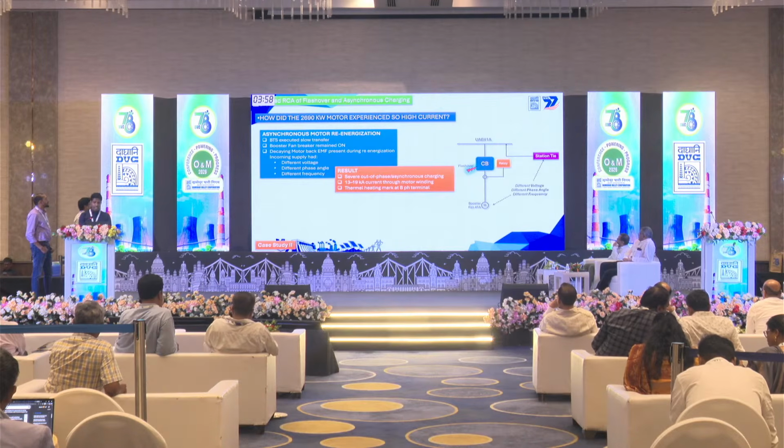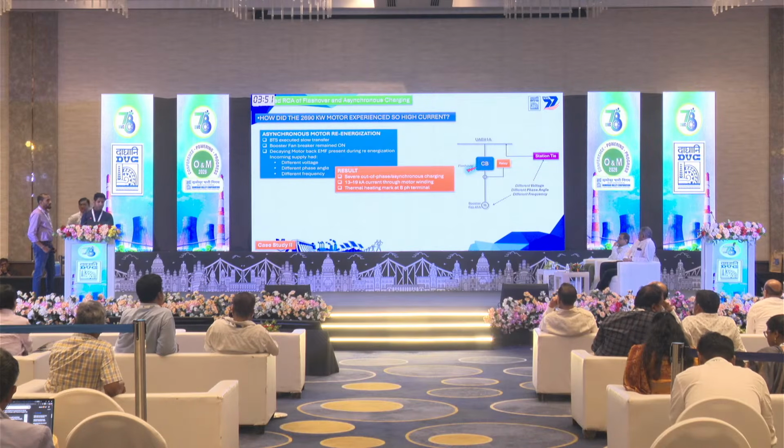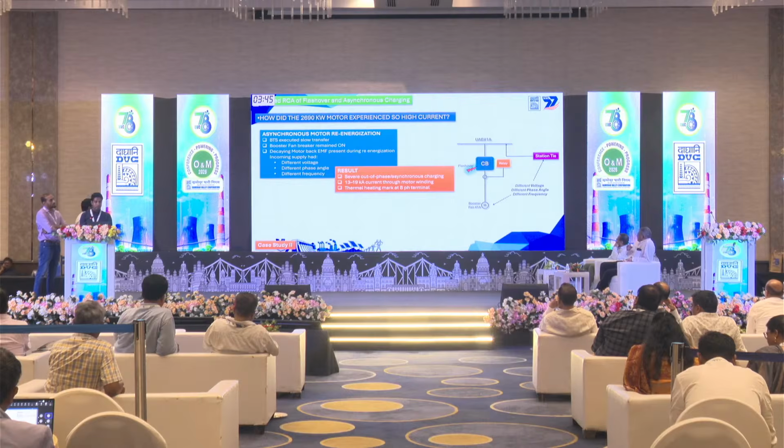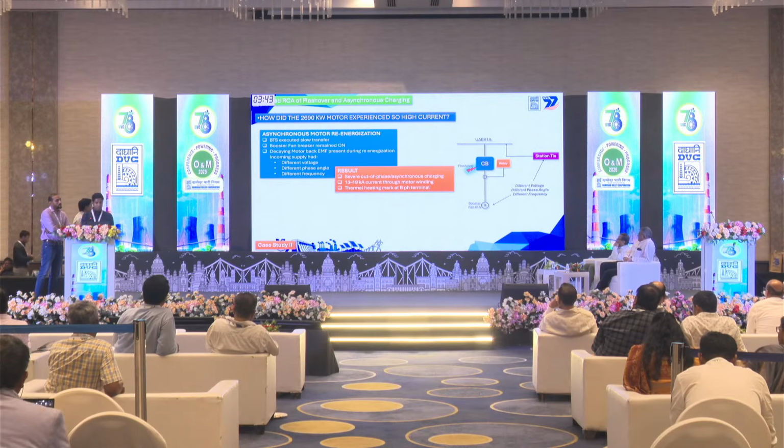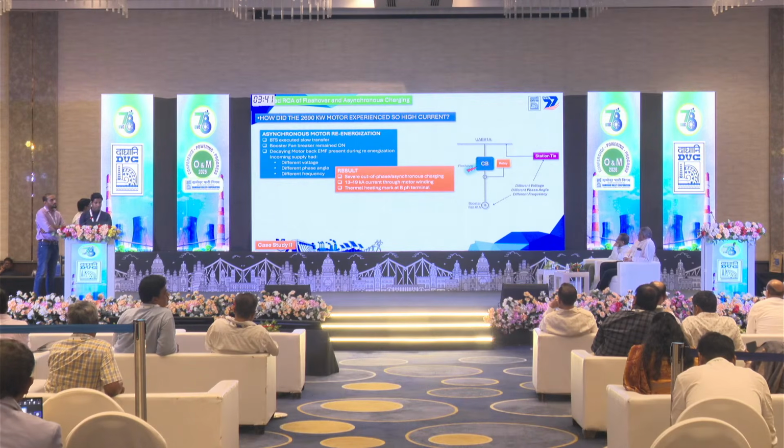Now, the station tie and motor bus have different phase angle and different frequency. So this creates severe out of phase or asynchronous charging. And for that reason, 19 kiloamps of current flowed through the motor. And we also observed a thermal heating mark at the B phase terminal.